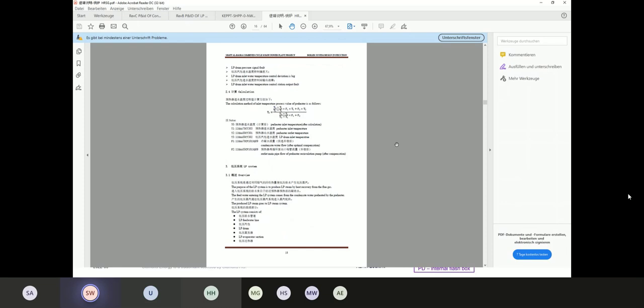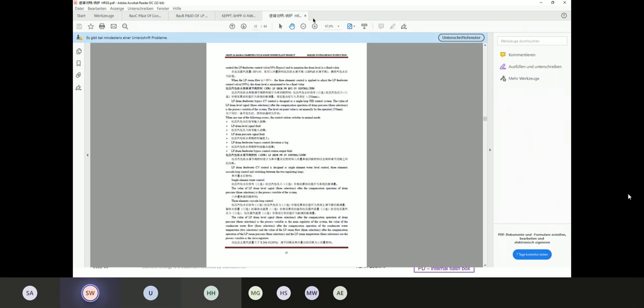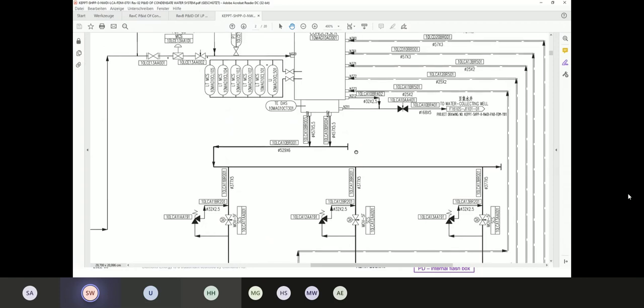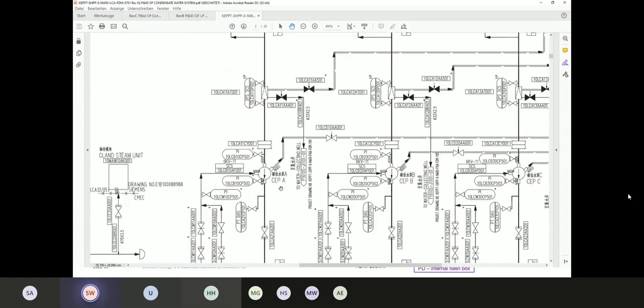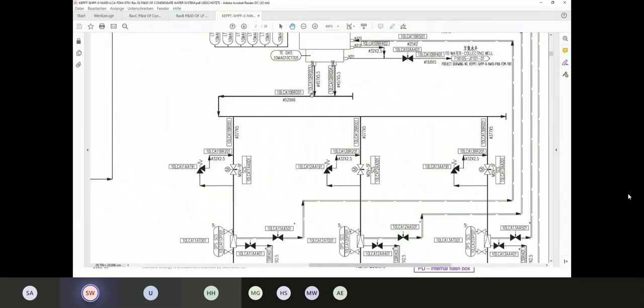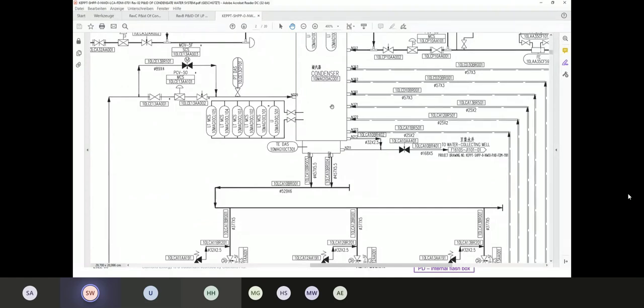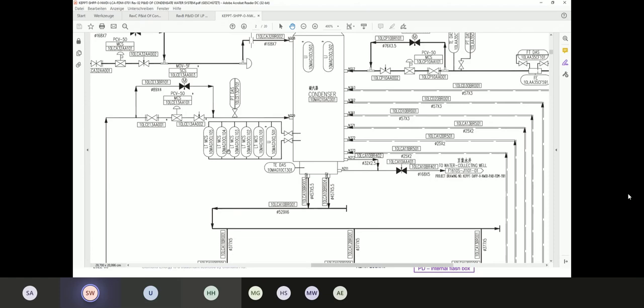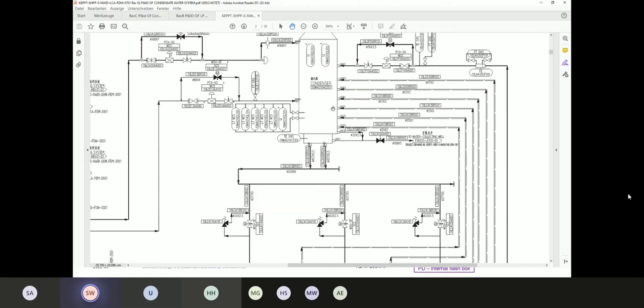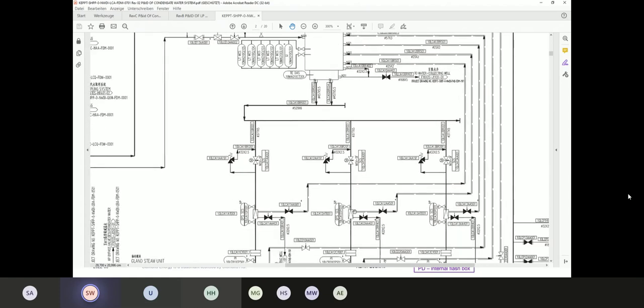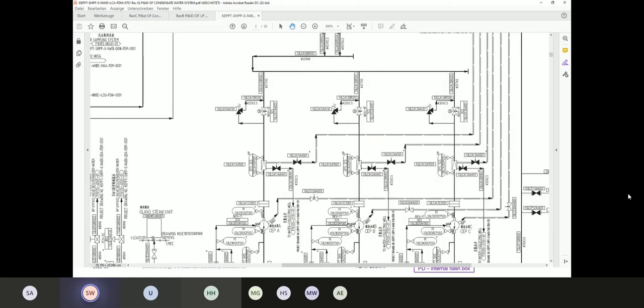documentation the value. I cannot see it right now, but you have for sure the value in here for the pump to start. Either it's combined with the level, so that they're just saying here the level needs to be higher than, I don't know, 300 millimeters or something. This is the normal way, I would say, that you have a certain level, and then you're saying with a certain level and the geodetic height, you have the certain suction side pressure here on the pump.